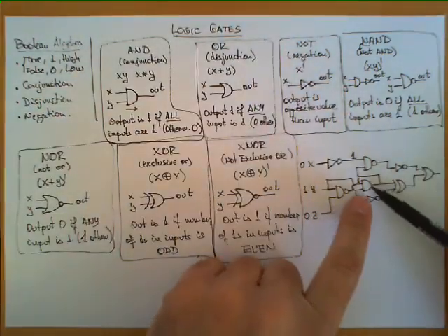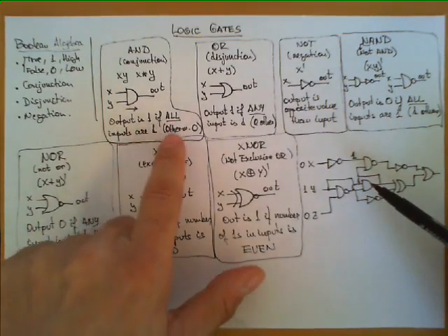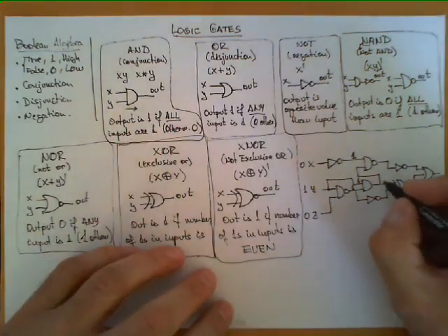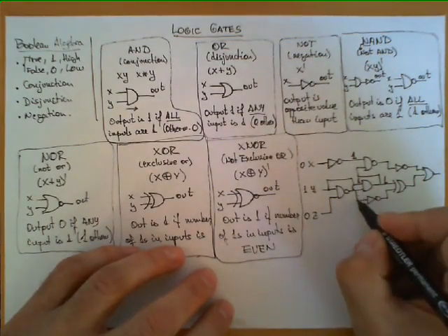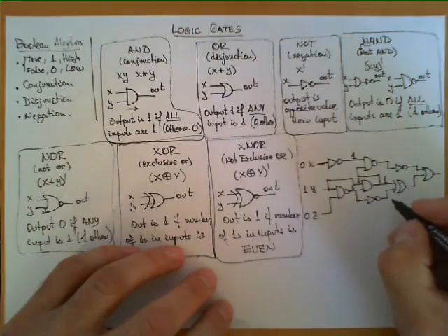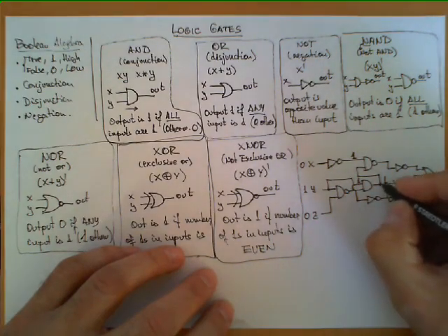Now look, this AND gate has both inputs at 1. When all inputs are 1, this output produces a 1, therefore this wire over here is going to have a 1. At the same time, this 1 in this wire will go through this inverter and produce a 0.